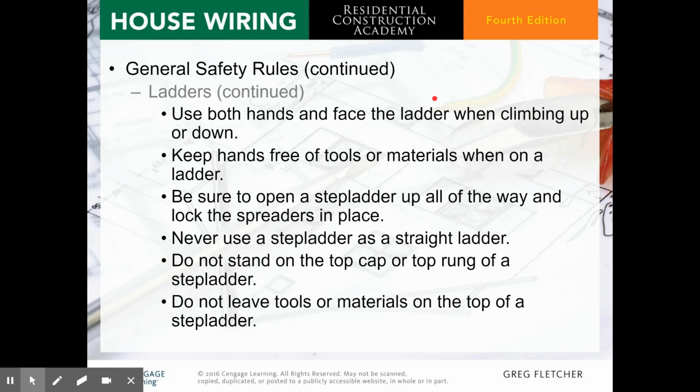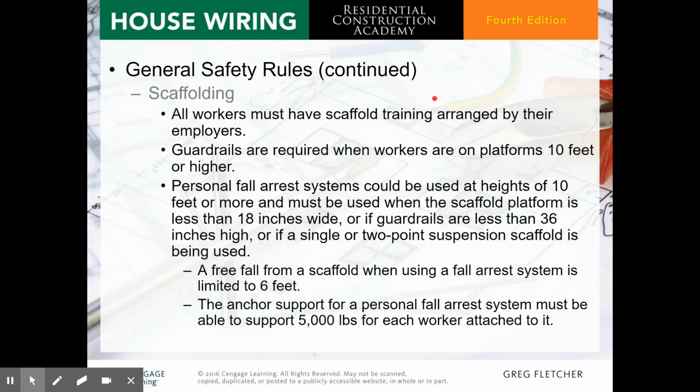Use both hands and face the ladder when climbing up or down. Keep hands free of tools or materials when on the ladder. Be sure to open a stepladder all the way and lock the spreaders in place. Never use a stepladder as a straight ladder. Do not stand on the top cap or rung of a stepladder. Do not leave tools or materials on the top of a stepladder.